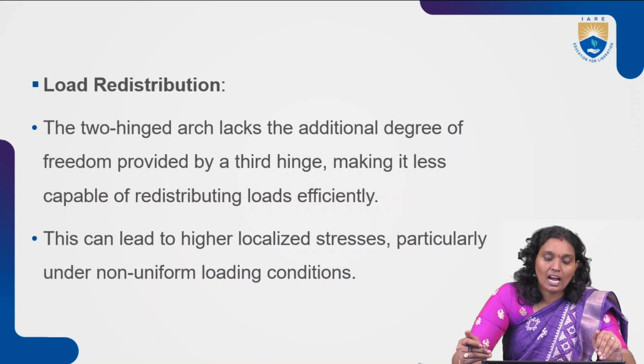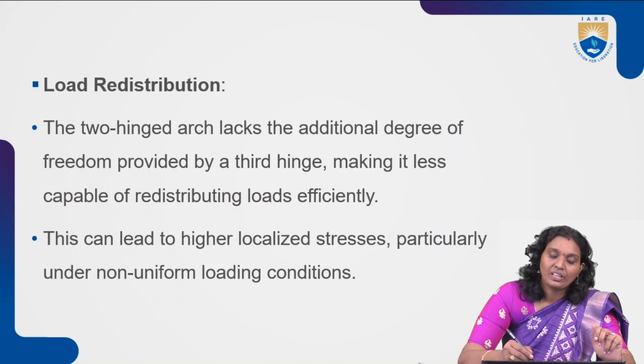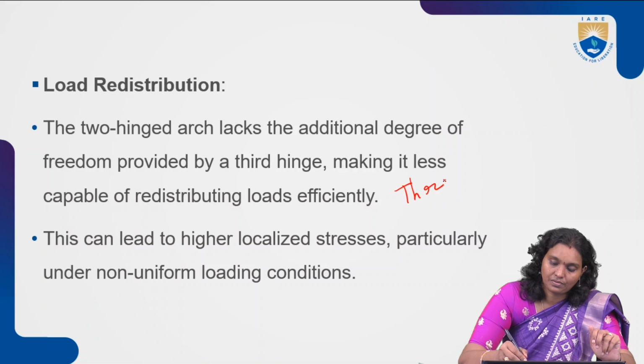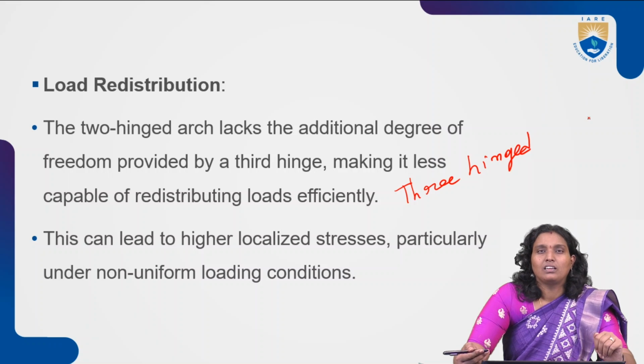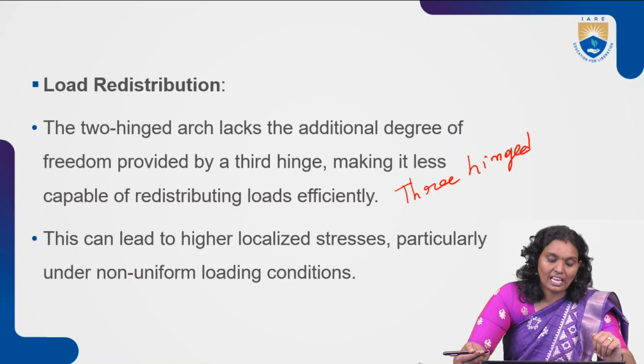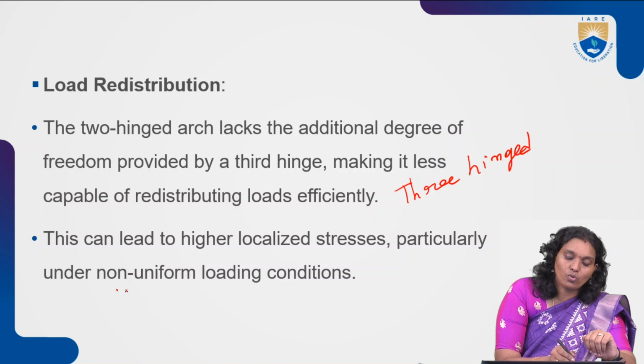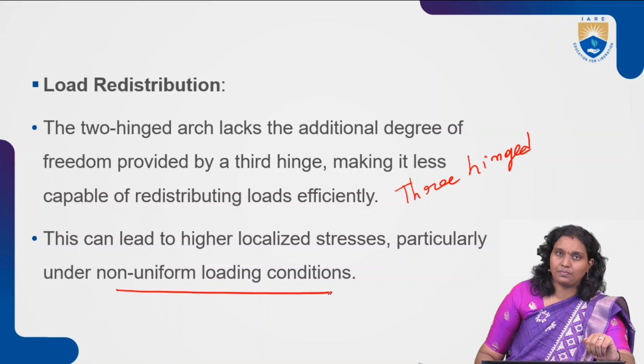The two-hinged arch lacks the additional degree of freedom provided by the third hinge, making it less capable of redistributing loads efficiently compared to the three-hinged arches. This can lead to higher localized stresses, particularly under non-uniform loading conditions.